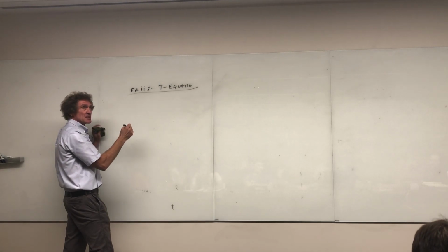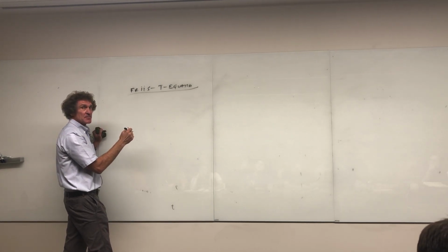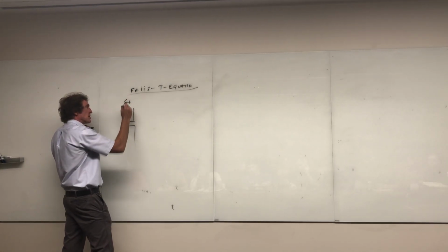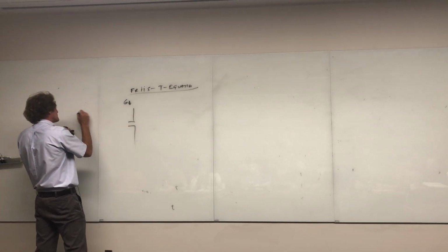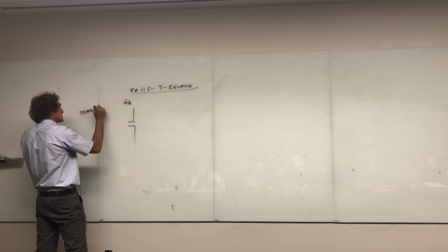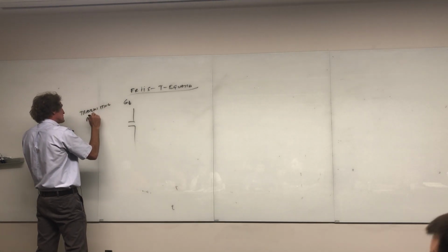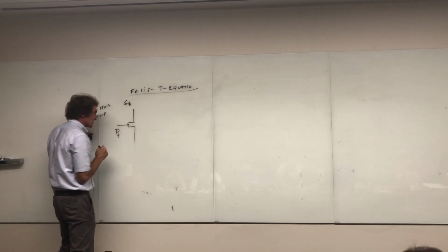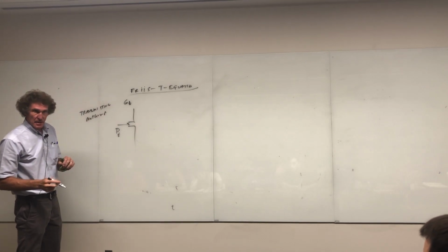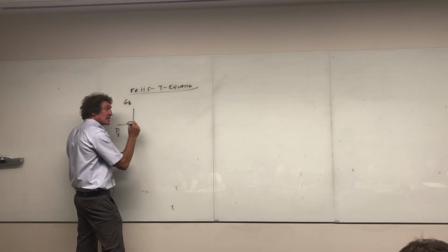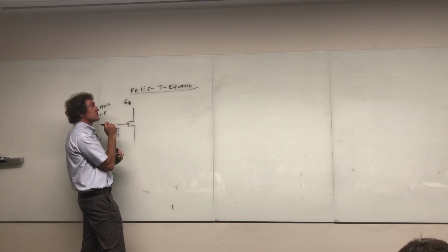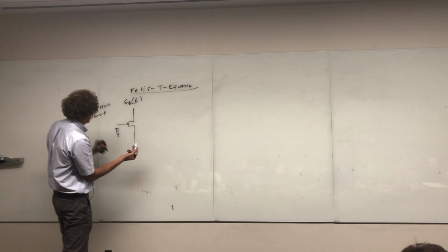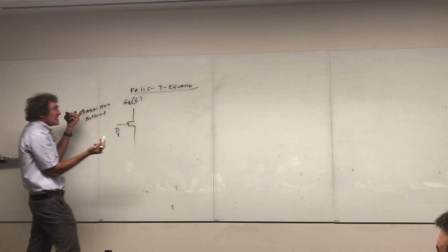All right, Friis transmission. Here's what the problem is, and I'm going to talk about some aspects of it that are important. I said it was a microwave length that can be anything. You're going to have a gain of a transmitter here. This is your transmitting antenna. In here, we're assuming that we transmitted a certain amount of power. Just call it PT for now. This has a gain. Now, we're going to assume that this gain right here is a function of theta, right? It's a function of phi, possibly. This is just an antenna. That's all I'm putting here. This just says transmitting antenna.